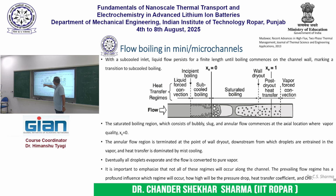So here if you see, the flow is entering, it is single phase flow, the boiling starts, and then you have annular flow, and eventually the liquid layer next to the wall dries out and you have a mist flow. As a thermal engineer, I would like to remain in this zone, but it is not trivial to maintain the nature of flow like this, because it is heavily dependent upon the flow rate and the overall pressure drop, right?